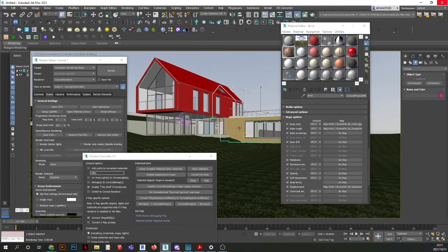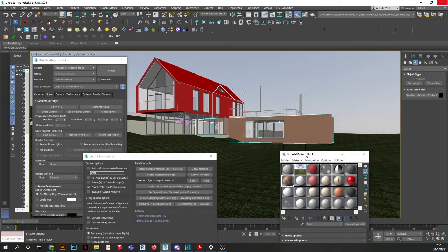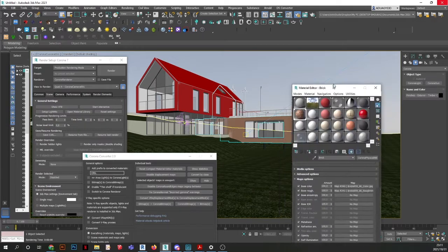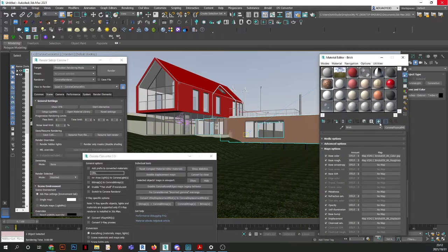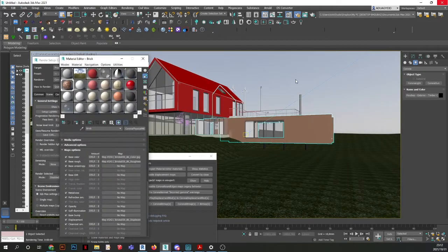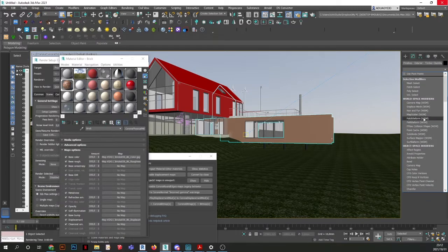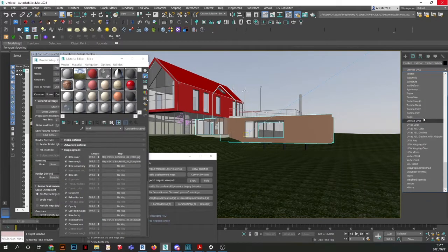to this. Okay, and you can see that we actually cannot really see the texture of the material. It is because we need to add a UV map to this wall. So if I click on it and I go to the modify tab, I can click on the modify list and just press U on my keyboard to look for UV map.